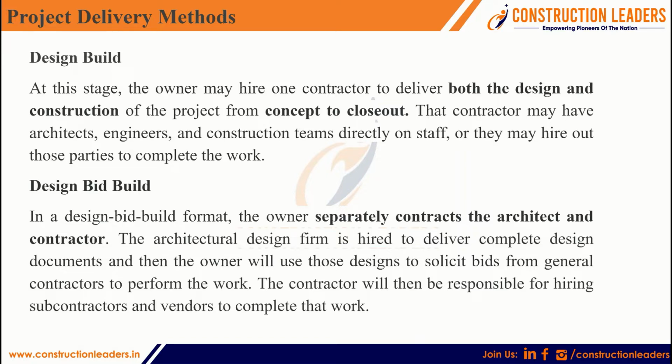I mean, here we are contacting one person and handing over all the responsibilities, meaning planning, designing and executing, to only one person or one firm or one contractor. That is design-build. If we contact one person and get the plan and design only, and if we go for an auction or a bid in between, and choose any other person to execute our plan and design, then it will be design-bid-build. I hope you are getting my point, right? A third person will be involved in design-bid-build.